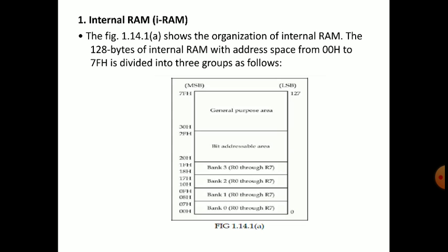See, we have the internal memory of 128 bytes. What is the hexadecimal equivalent of 128 actually? 128 means 16 into 8, so 80H is the equivalent of 128, but we are considering from the memory location starting at 00H.